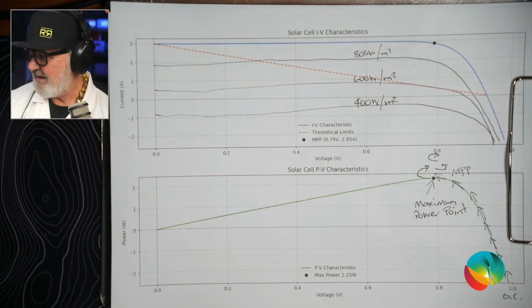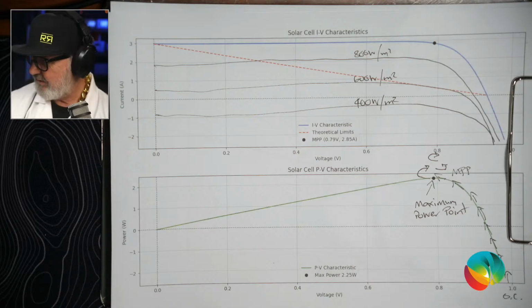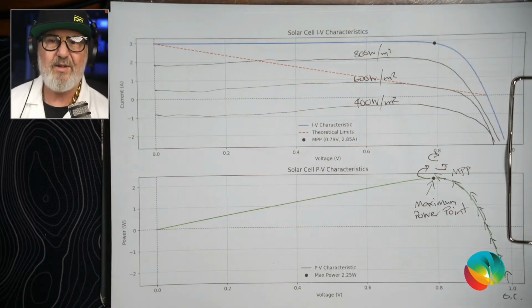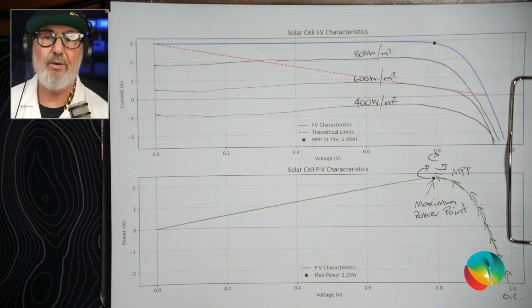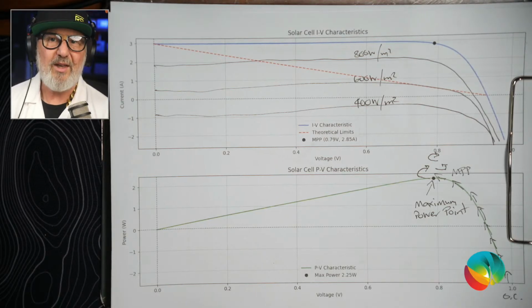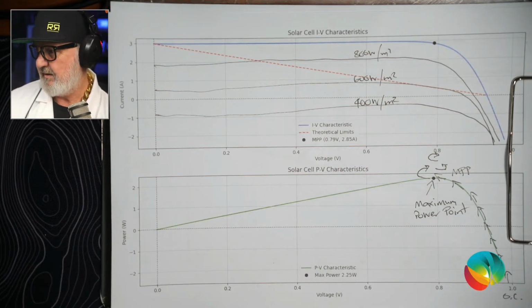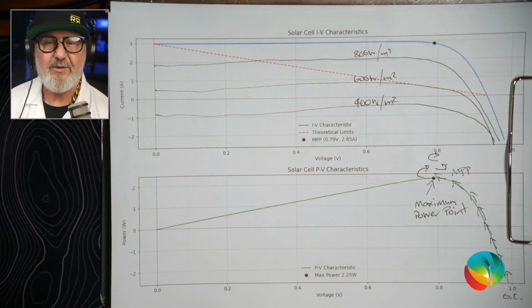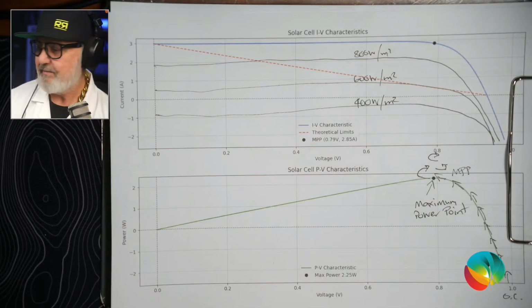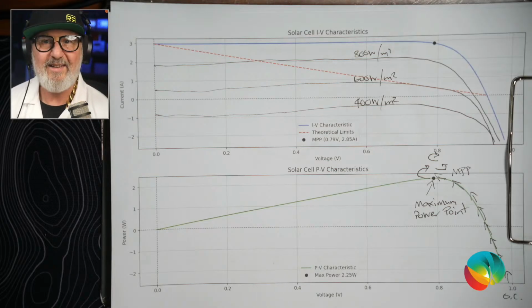And I've got Yakety90, and he says, I'm writing up an ARL Earth Guard with a Victron 250. That's right. So ARL actually makes a standalone earth fault detection device, and it's called Earth Guard. So you can compare that with an existing MPPT. In this case, he's doing it on a Victron 250/100. In Victron speak, 250 means the maximum voltage, and after the slash is the output current, so 100 amps. So good timing, eh? Yeah, indeed.